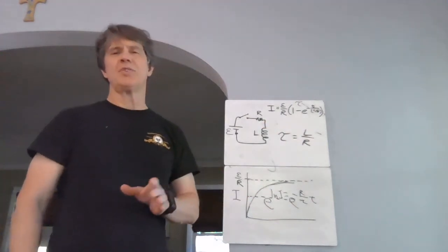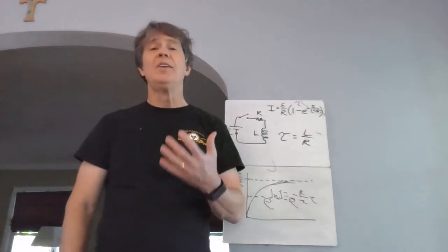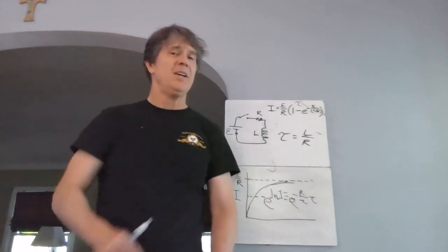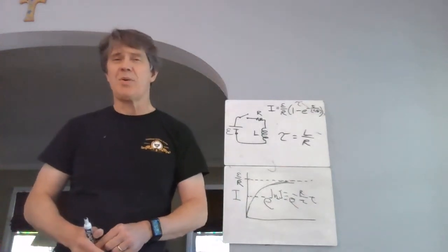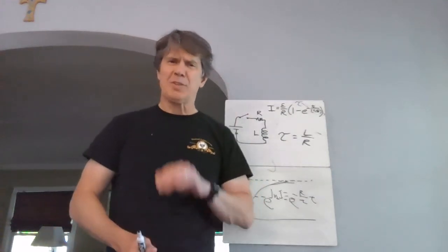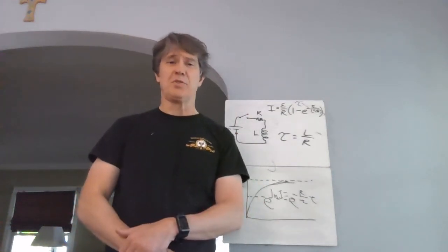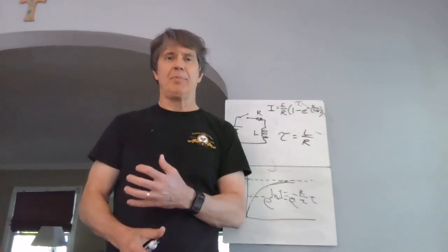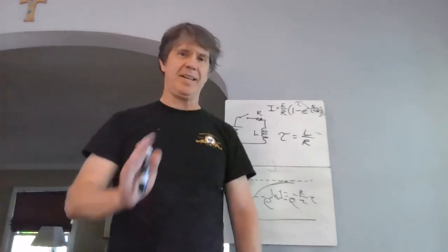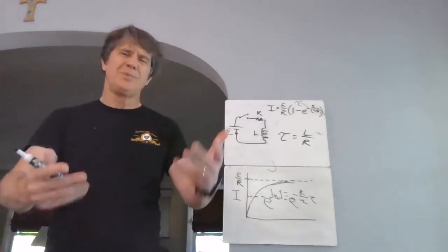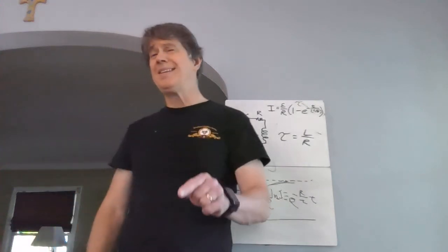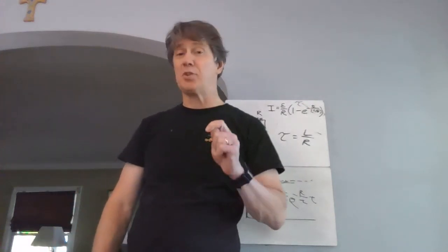Now you've seen an RL circuit. Any real circuit in the world, even if it's just a wire that makes a turn a little bit, already has some inductance right there. So actual currents don't instantaneously shoot up to a final value just because you flip a switch. Actually, there's a very rapid response, and it quickly levels off. Or if you put a big inductor in there, it takes a while. One reason you might do it is some kind of surge protection, but there are other interesting things. What really gets neat is when you put them in there with a capacitor too.